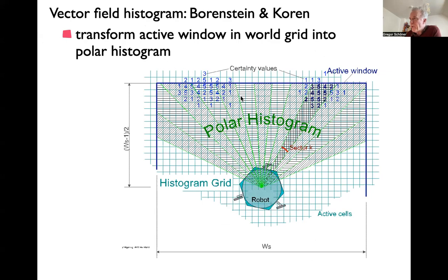by accumulating evidence across time, you can get essentially a world map. And for that, you have to know where the robot is at every moment in time. That is, you have to integrate your motor commands to estimate where the robot is. And then that's how you can enter the sensor signals into the grids, right? Because you have to know that this is the same pixel that you made an entry in earlier, that your sensor is now pointing to, right? For that, you have to estimate where you are, and they have some approach for that.